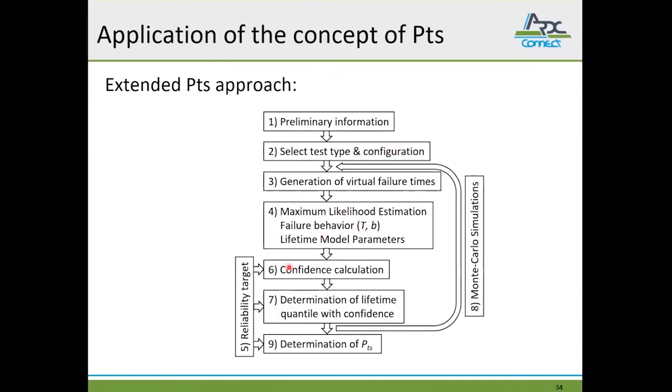And then we keep going on with our classic Weibull analysis to determine the confidence and then the lifetime that we can demonstrate within this simulation step. Then we repeat the simulation step a lot of times, and then we can determine our probability of test success considering our reliability target.